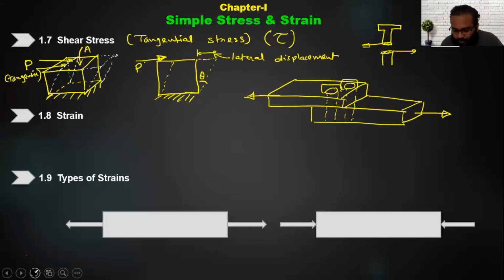Okay, Tushar, I'm coming back to your point. Suppose this is my paper, and this is the plane of the paper. I'm using the scissor like this. So my scissor is perpendicular to the plane of the paper, but you see the cutting edge of the scissor. How is it with respect to the cross section? Tangential. I'm talking about this cross section, not this one. This is the face of the paper. This is the cross section of the paper, right? Can you see this? Yes, sir. So I am applying the force tangential to this cross section. I cannot cut the paper by applying force on top of the face; I have to cut it tangentially to the cross section, right? So I'm applying force with the scissor parallel to the cross section. That is why it is shear stress, not normal. I hope I answered your query.